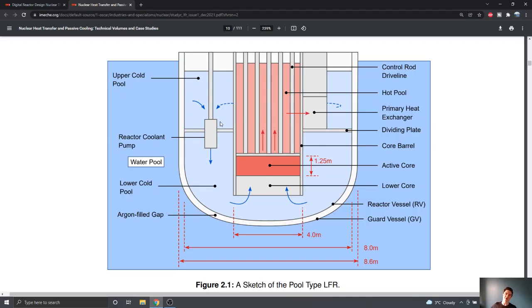So if you think of the power lines which are providing electricity to the nuclear power station, if there's a power cut for some reason or an uncontrolled blackout, what will happen first of all is that the pump, which needs electricity to drive and push the fluid around the reactor, will slowly spool down and shut down.